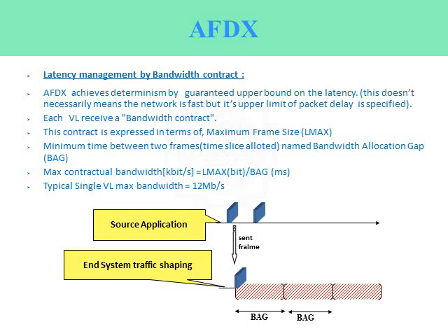It won't be transmitted immediately, unlike in IEEE 802.3 Ethernet. It will be skipped and transmitted from the starting point of the next BAG value, as shown here. And similarly, now you see from that BAG value, the packet is not at the start, so it will be skipped and delayed further.